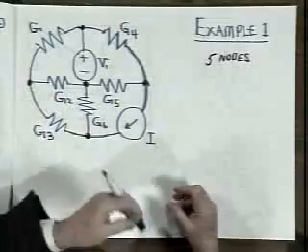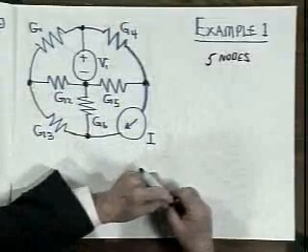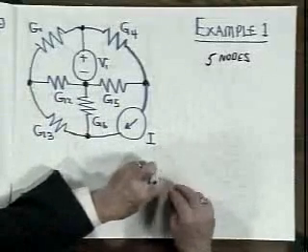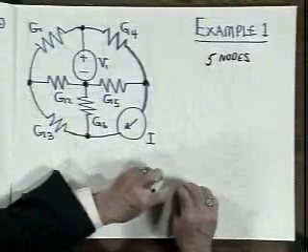Now, in this network, I could choose any of these 5 nodes as a reference node and say that at that node, by definition, arbitrarily, the voltage is 0. Then we define voltages at all the other nodes. These become node to reference voltages. And with those voltages in hand, we proceed to express the currents out of each node in terms of the voltages and the element definitions.